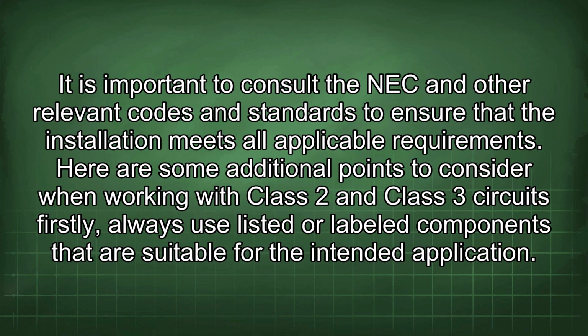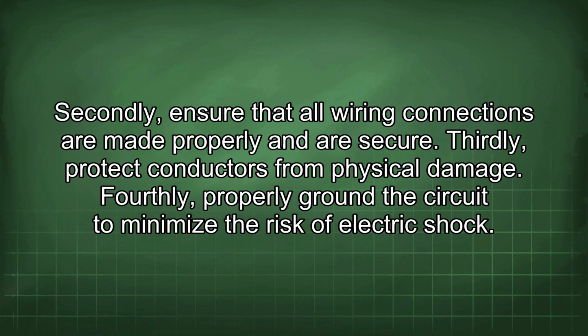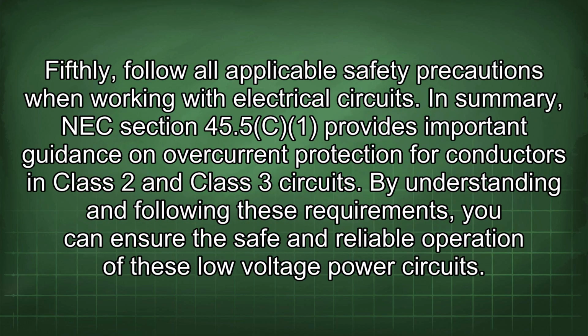Firstly, always use listed or labeled components that are suitable for the intended application. Secondly, ensure that all wiring connections are made properly and are secure. Thirdly, protect conductors from physical damage. Fourthly, properly ground the circuit to minimize the risk of electric shock. Fifthly, follow all applicable safety precautions when working with electrical circuits.